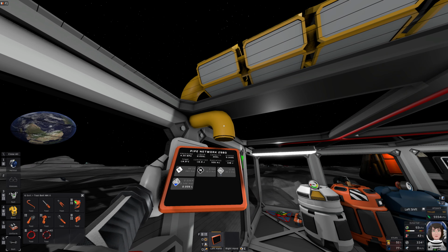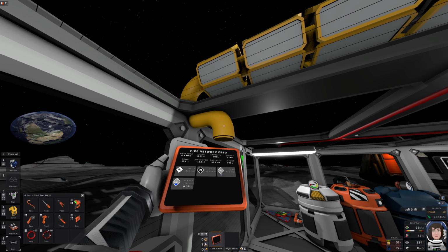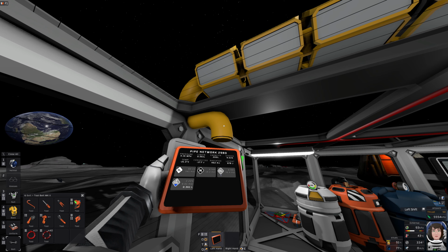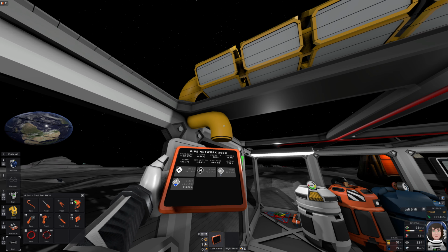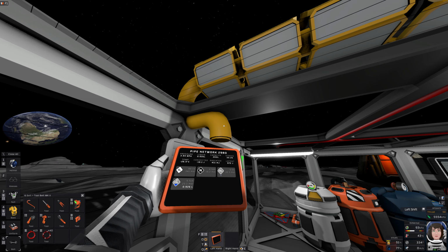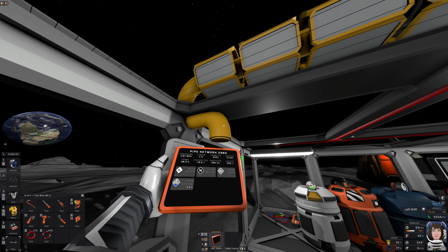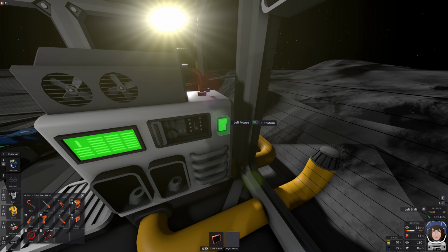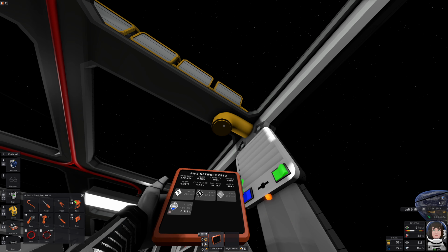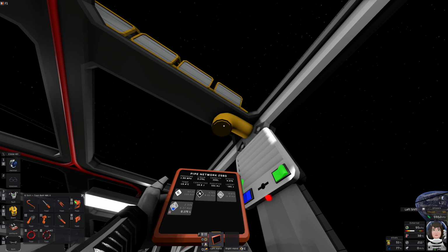First of all, look at the pipe. Minus 15 degrees? What's happening? Well, what's happening is that it has not been evacuated. The vents just turned on and then they turned off. There are 4 megapascals in there. It's completely out of control. This is not how you set this thing up, man. So let's turn off the filtration and pump the pipe empty. Waste tank caution.